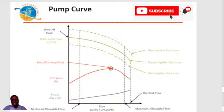Now, if you look at the shape of the efficiency curve, it simply means that as you move away from the best efficiency point, the efficiency of the pump drops. As you move further away, either to the left or to the right, you can see the shape of the efficiency curve.